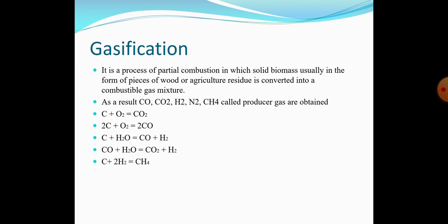The definition suggests that gasification is a process of partial combustion in which solid biomass, usually in the form of pieces of wood or agriculture residue, is converted into a combustible gas mixture. As it is said that it happens in partial combustion, not full combustion. Partial combustion occurs because the air supply is intentionally kept less than the amount required for the complete combustion